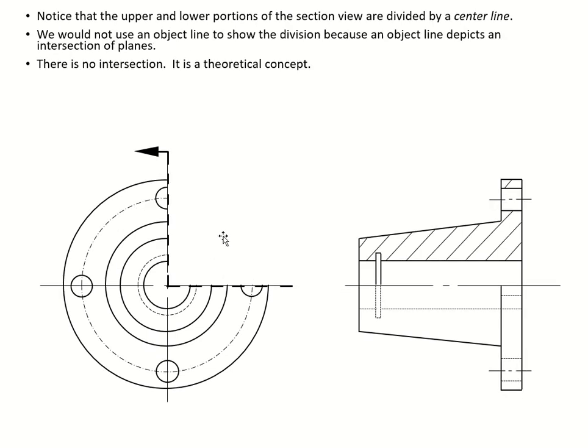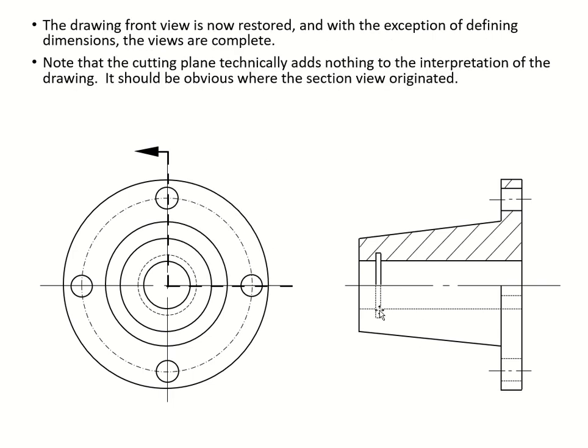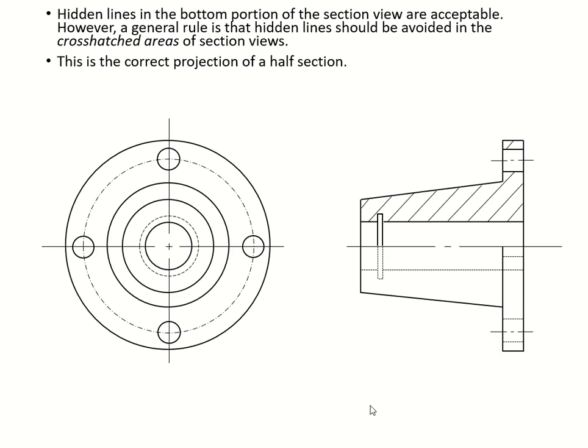All right, and we remove the cut, so you can see that's how you're seeing along that edge, going inside to your right side. And then, of course, after you have finished and drawn your right side, we're going to put that removed part back into our front view. Okay, so this is your completed section view.